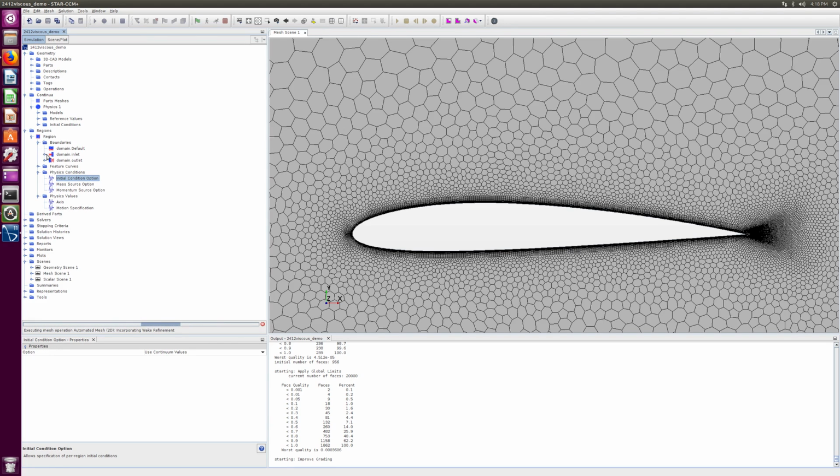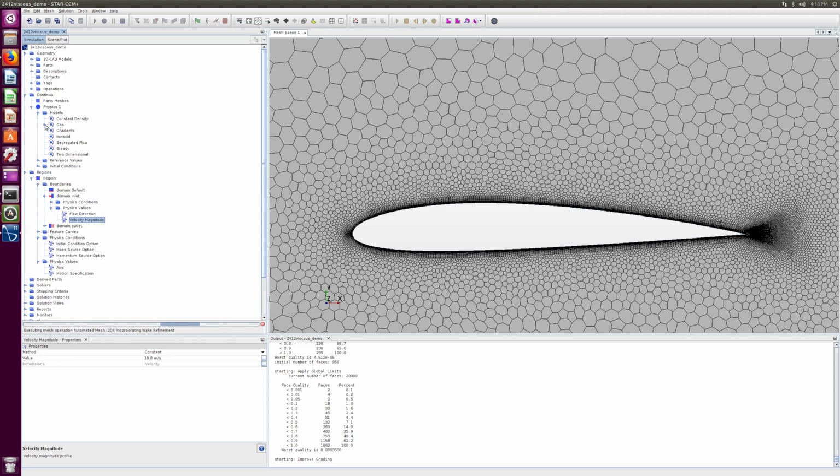Okay, here we go. So I'm going to change my velocity. I right now have it set at 10, and I did that just arbitrarily. It didn't matter because I was doing an inviscid. I just normalized everything. But now I need to get the right Reynolds number. So first I need to know the density and the viscosity. I haven't turned on the turbulence, so it's not going to show me viscosity, but I know what the default is. So I'm going to just use it.